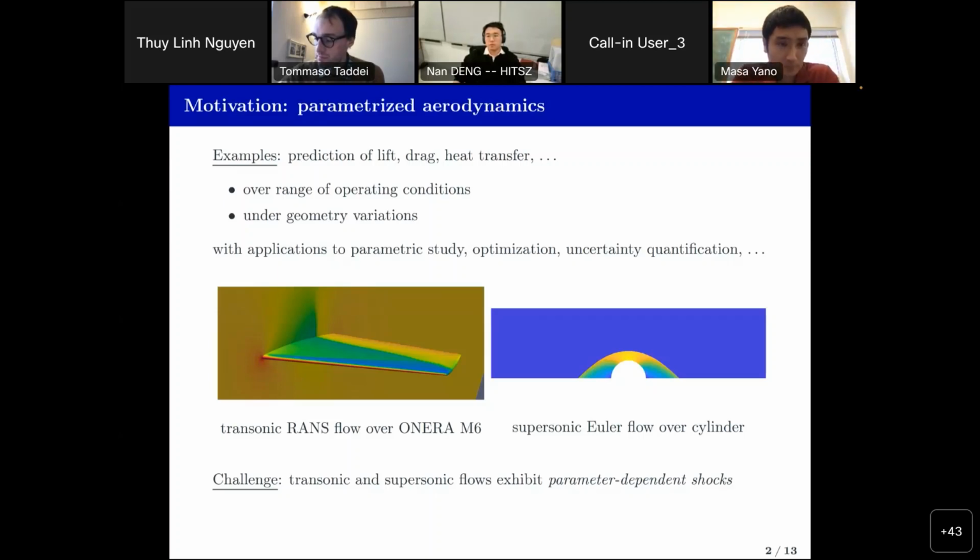They require really fine grids. You have shocks that move around, so the most appropriate grid for a given test case changes. So standard practice is to either use some very fancy adaptive mesh refinement, or just predetermine where your shock and moving feature is going to be and refine that whole area heavily. It just leads to challenging large-scale problems, and that becomes an issue, of course, when we want to vary parameters and solve many parameter configurations.